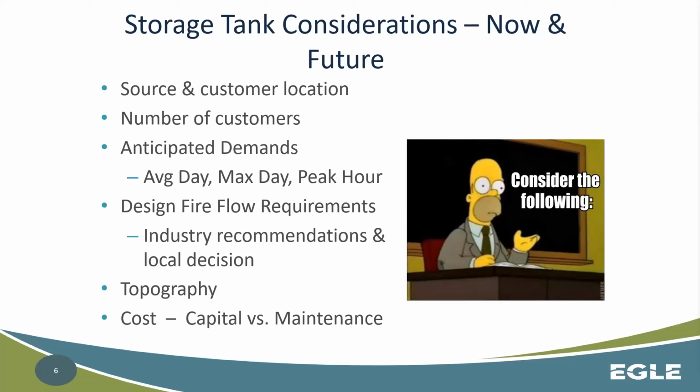Maybe you're in a hilly location. Maybe it's more beneficial to put that tank up on top of that hill, so you constantly have that pressure going on. Yes, you'll probably have to pump up to it depending on the situation, but at least you have that reliability that you're always going to have pressure as long as that tower, or that storage tank in general, is filled.